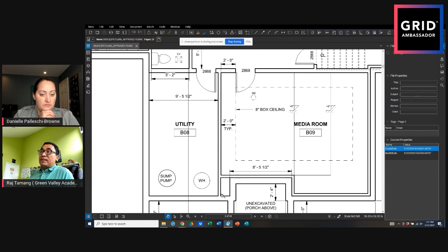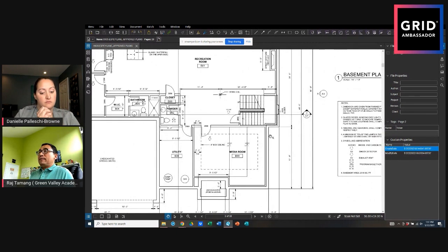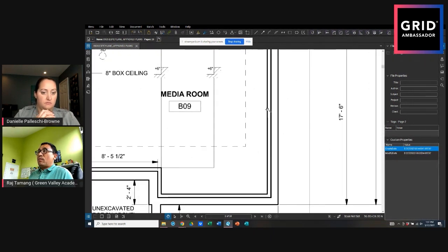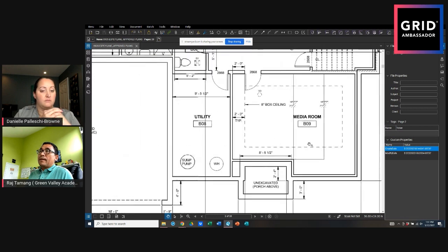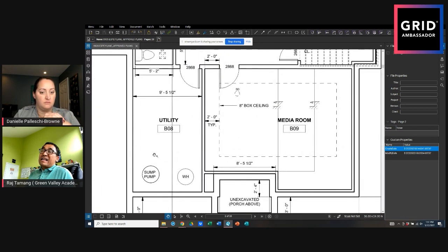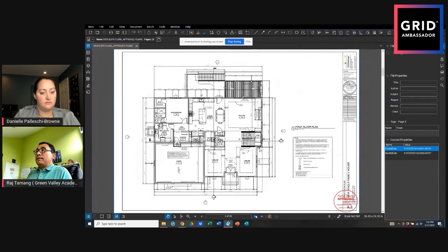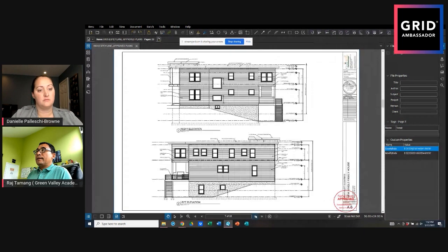So the insulation has to be provided in the basement, right? That's usually R13. Inside, you see this is a 2x4 wall. But here you do, I think, R11, but blanket. You see that's a blanket, right? You screw or nail it into the concrete wall, but you still have to provide the insulation, but those are cheaper, R11 blanket. So you do blanket here. This is regular insulation.